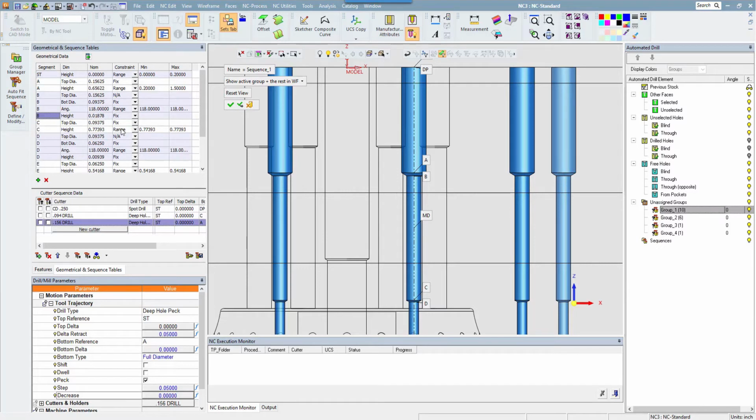We can set a range on all of these options for B, or we can tell it just to ignore it. I mean, if that angle is slightly different, I really don't care. It's not important in this situation. What really matters to me are these diameters, that those are the same. So for the chamfer between them, I'm just going to say NA. Why sit here and fight it if we don't have to?